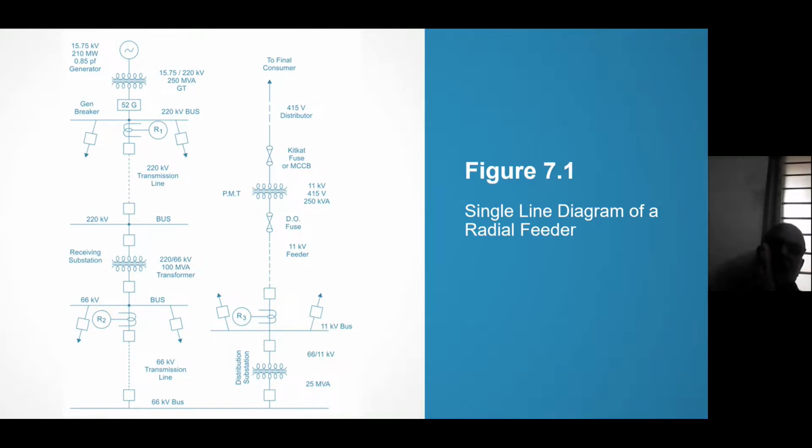And also, if you reduce the area, then I squared R losses will be high and the efficiency of transmission will be bad. Therefore, I have to step up. The day on which the transformer was invented, the scenario of electricity changed. And now we are stepping it up from 15.75 kV to 220 kV.